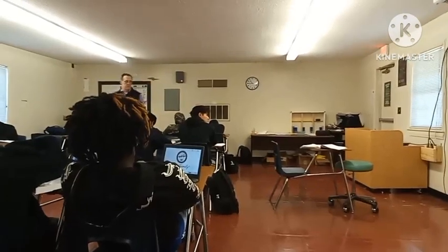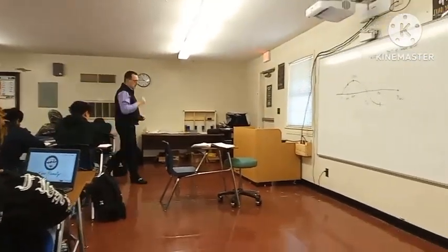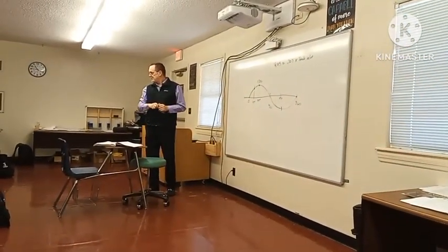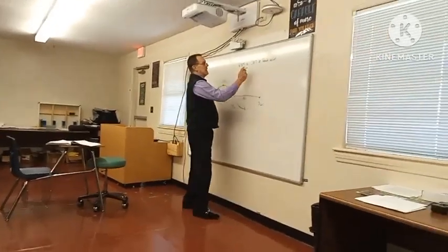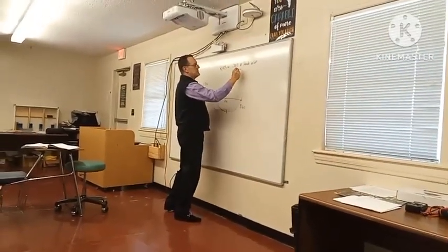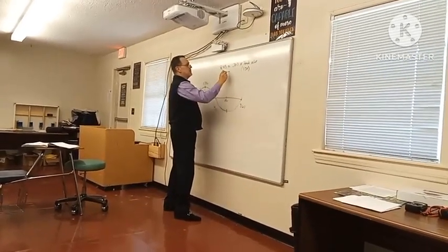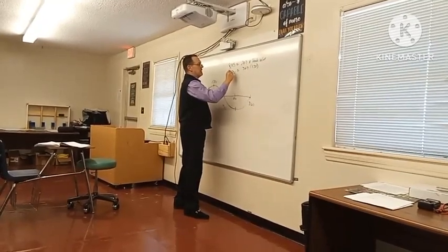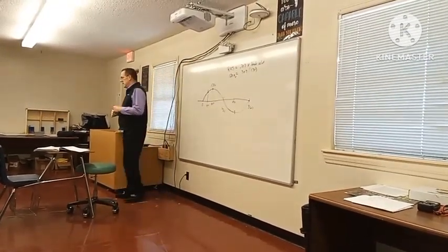We're going to multiply times what? 0.707. So 0.707 times that 170 gives you 120.19 volts as the RMS.